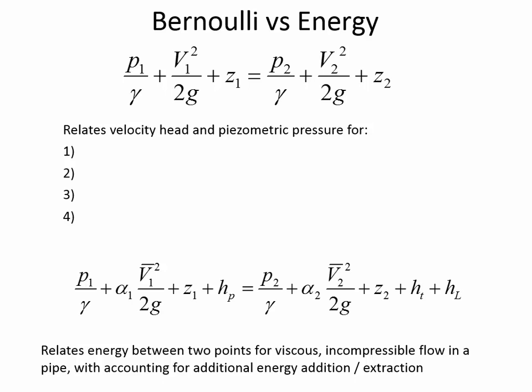And that's very important because what we're saying is if the water goes from 1 towards 2, it's losing energy as it does that. That's why the water goes from 1 to 2, because location 2 is a lower energy state. And so the flow goes towards where the energy is lower. For example, water flows downhill, right? Well, in a pipe, water flows from high pressure towards low pressure. And so the water goes towards the low energy state, and this H sub L, the head loss term, accounts for how much energy is lost between 1 and 2 due to the pipe friction and local losses. Now, we also need to keep track of 1 versus 2 because the pump term is adding energy.